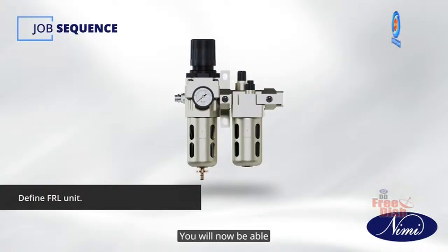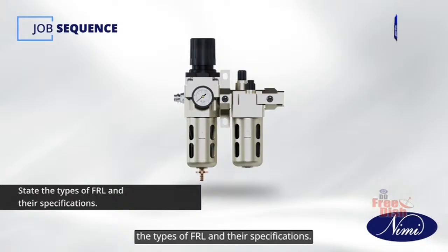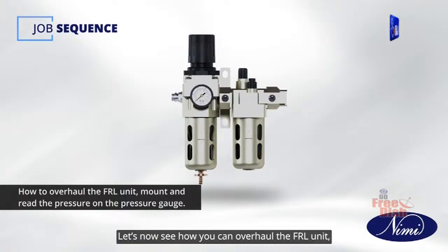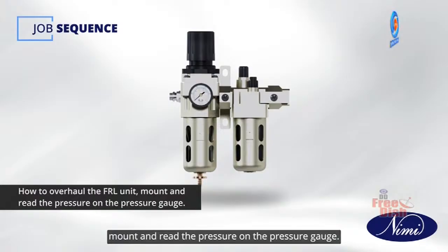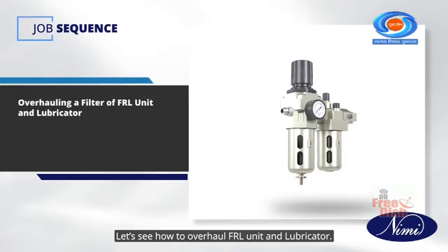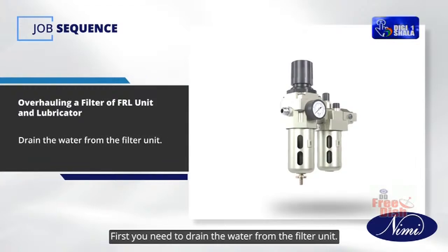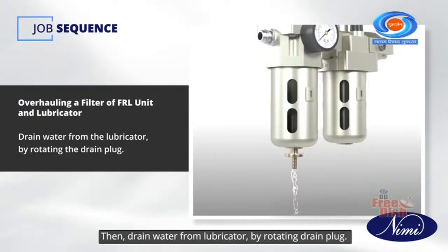You will now be able to define FRL unit and state the types of FRL and their specifications. Let's now see how you can overhaul the FRL unit, mount and read the pressure on the pressure gauge. Let's see how to overhaul FRL unit and lubricator. First, you need to drain the water from the filter unit. Then, drain water from lubricator by rotating drain plug.